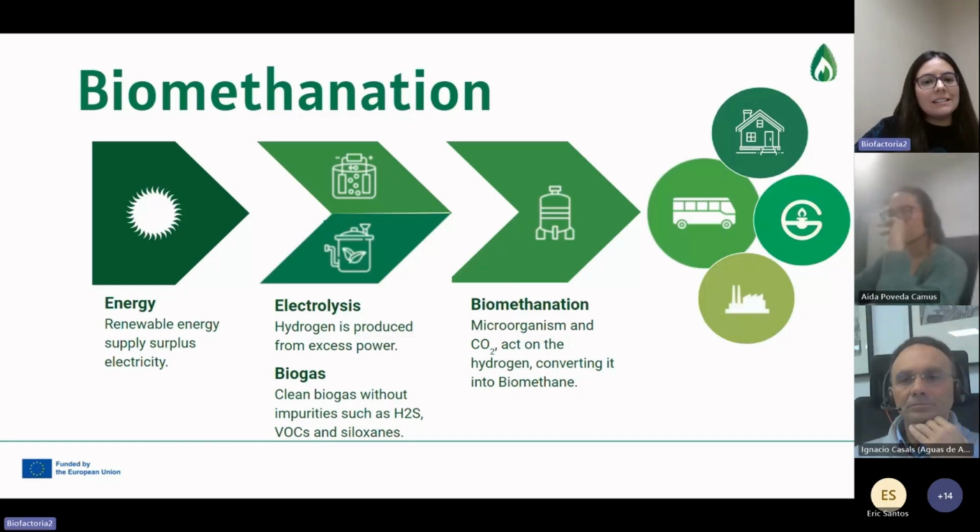The hydrogen is supplied by an on-site electrolyzer powered by renewable electricity, where the regenerated water from the tertiary system of the wastewater treatment plant will be pumped through the reverse osmosis systems to generate the mineralized water for the electrolyzer.